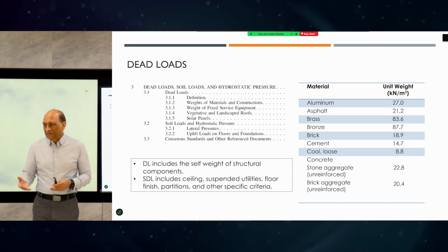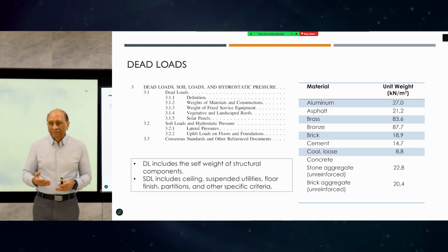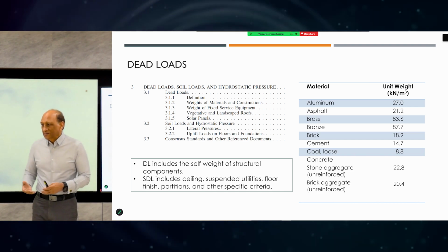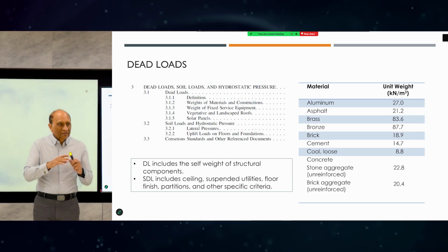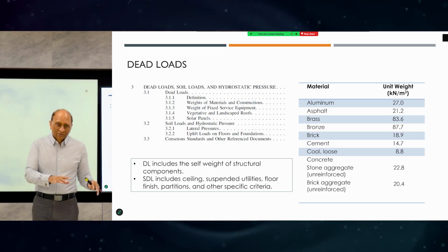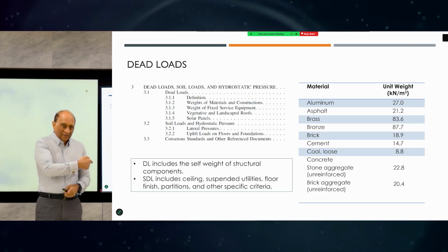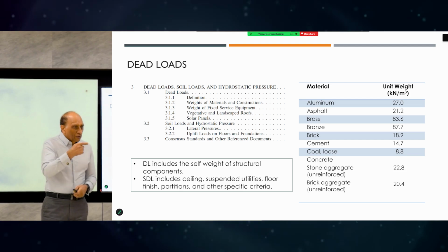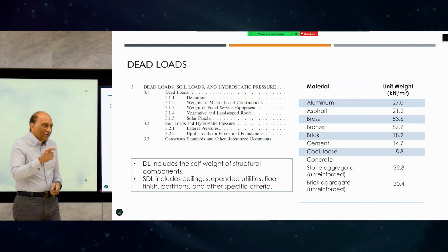And that resonance effect increases the displacement and load many times. If you don't analyze it specially, then you cannot handle it, because the code loads are not for a specific structure. So even if you follow the code, the safety was not guaranteed. The intent of the design was to make it safe, but it was not. And this happens quite often.